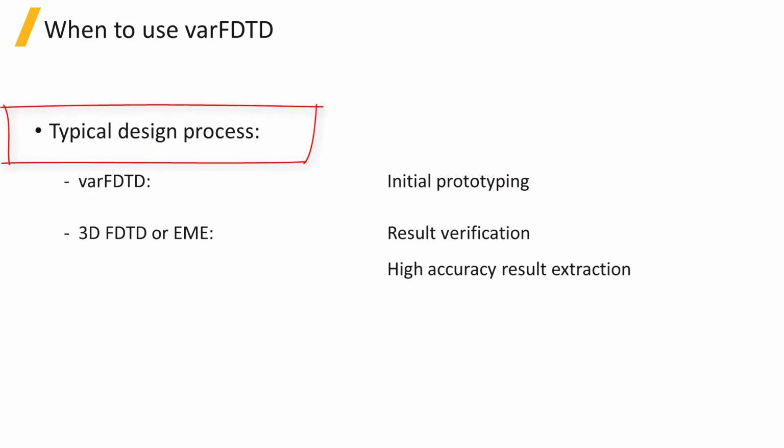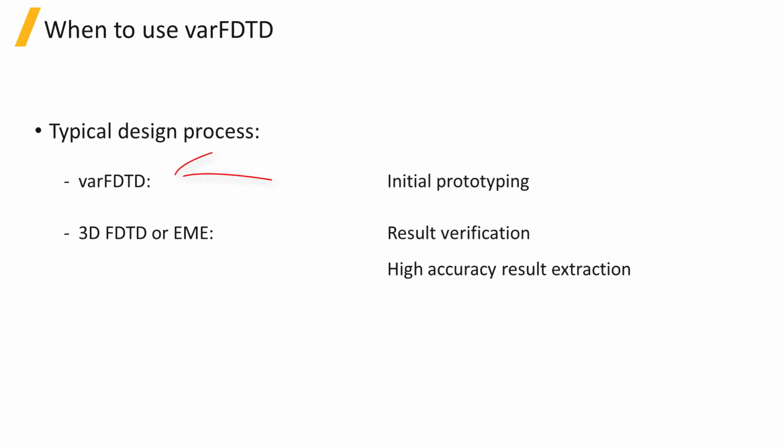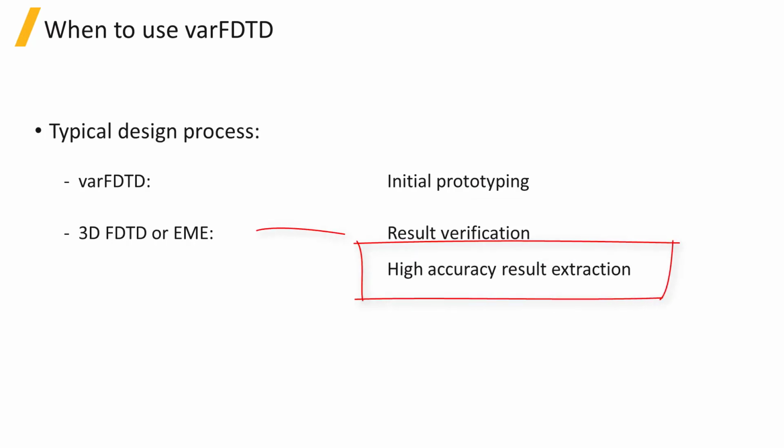A typical design process is to start by using the varFDTD solver for initial prototyping to determine a range of design parameters that optimizes the performance of the device, followed by verification of the results and extracting high-accuracy results using 3D FDTD or EME simulations.